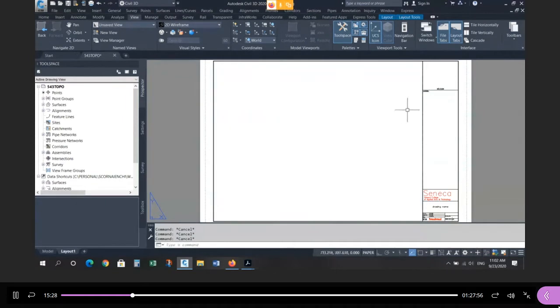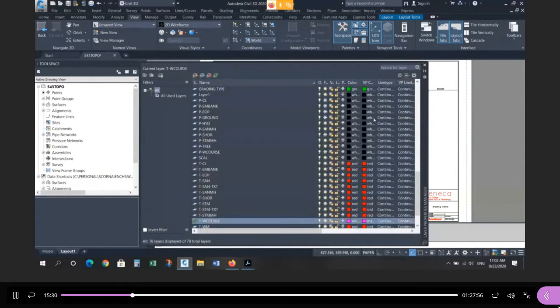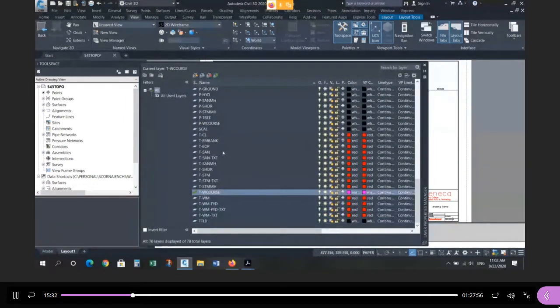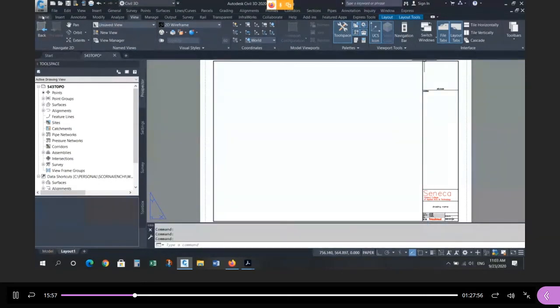So view. To do this, I usually put it on a layer called viewport. Again, if it's not there, I would create it. So I usually create a layer called viewport. And that viewport layer, I don't want to see the frame. So I'm going to make it non-print. And that's how you can see it in the drawing, but it won't show up on paper or a PDF, right? So when you print this layer, whatever's on it won't show. Okay? So I'm going to make it current, and it will not print. So now it should be current.